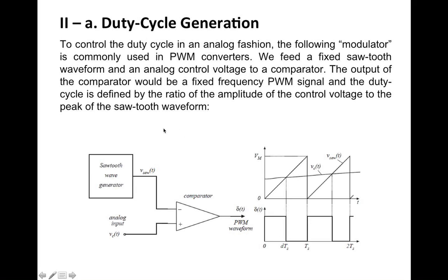Turns out that this whole block, in terms of AC response, is an attenuator, and the attenuation factor is 1 over the amplitude voltage of the sawtooth waveform. So it doesn't have any dynamic response. It's basically just a gain or an attenuation.